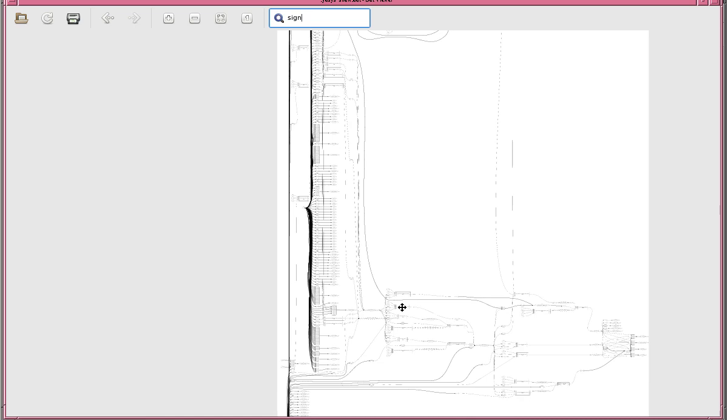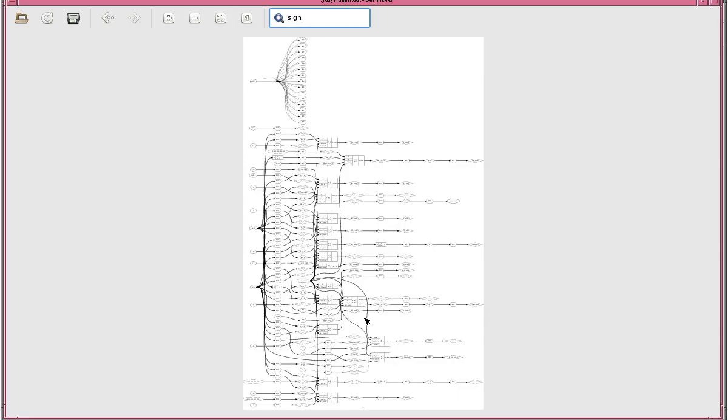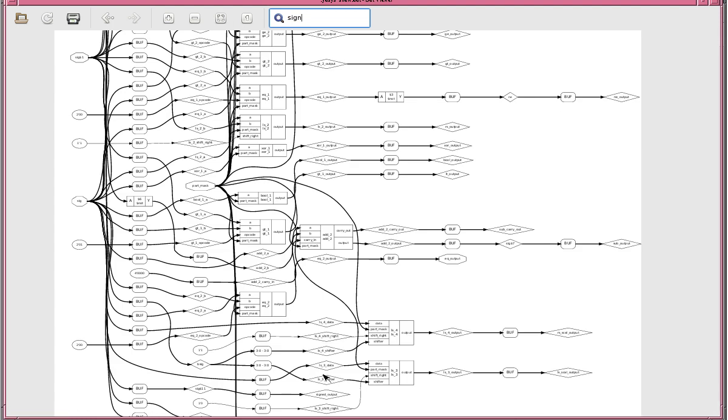So let's now load that in again. Control D, Yosys. Read ilang that file, proc, synth. So show top again. Let's have a look at that. We're back to that top level design there. And now I'm going to run proc and synth. No, I'm not going to do that. I'm going to do read_ilang and just plain synth. Now this will use a default standard cell library. And it's taking forever. Show. Okay, it's finished and it's done.